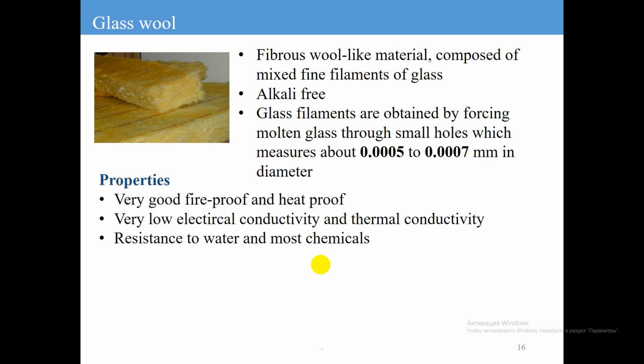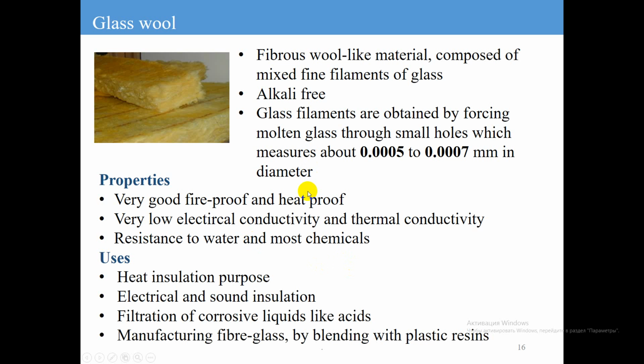Properties: very good fireproof and heat-proof, very low electrical conductivity and thermal conductivity, resistance to water and most chemicals. Uses: heat insulation, electrical and sound insulation, filtration of corrosive liquids like acids, and manufacturing fiber glass by blending with plastic resins.